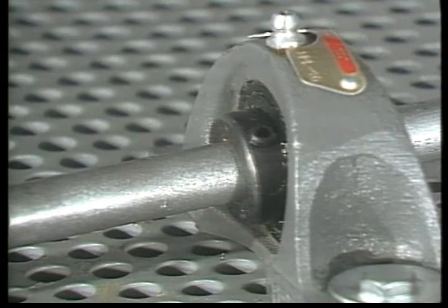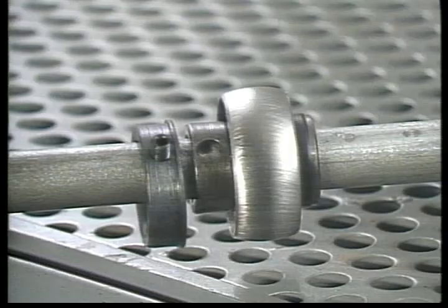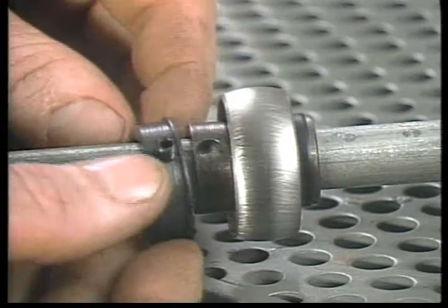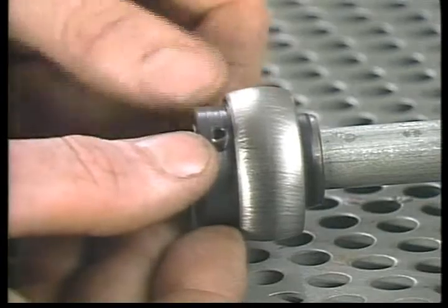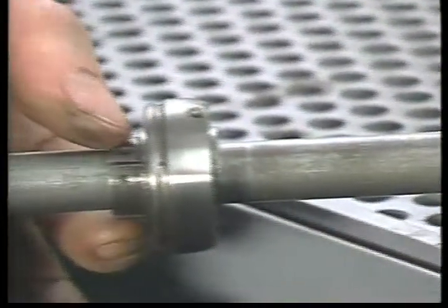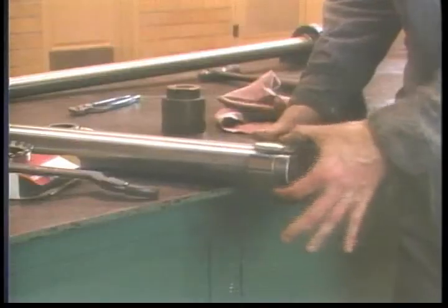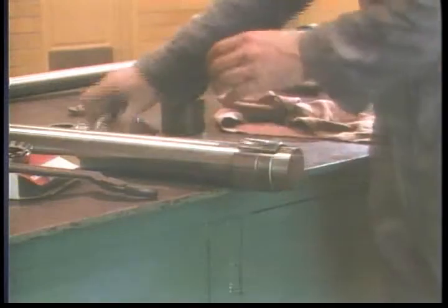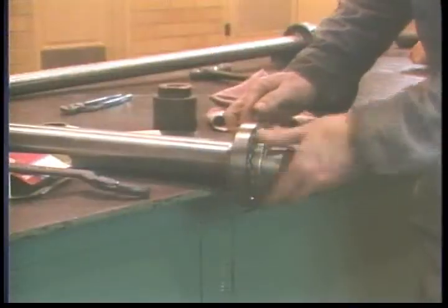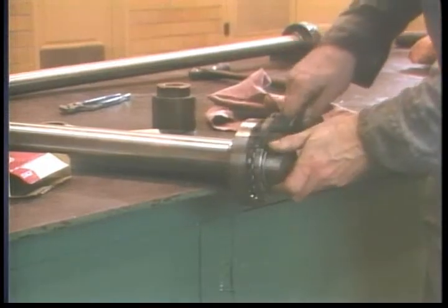Inner rings are often locked mechanically. A common method is the use of set screws connecting through an extension of the inner ring. There are various kinds of locking collars. In some, the set screws go through the inner ring to the shaft. In others, a clamp squeezes the bearing's inner ring tight on the shaft. Large bearings often use a tapered adapter sleeve. The tightness of the fit is adjustable with the nut, which forces the bearing inner ring tight on the tapered sleeve.